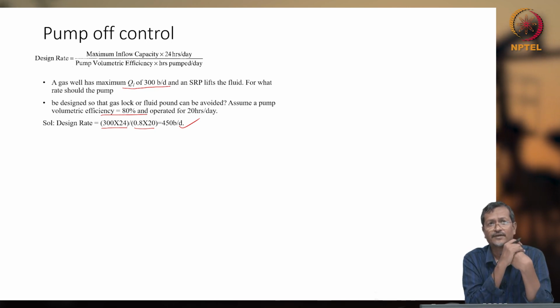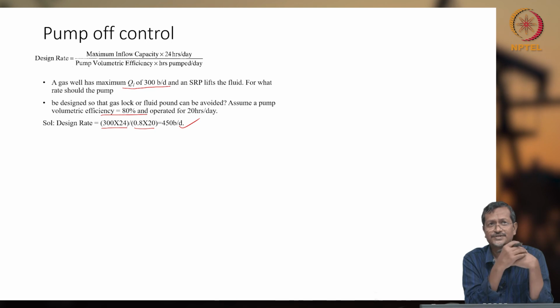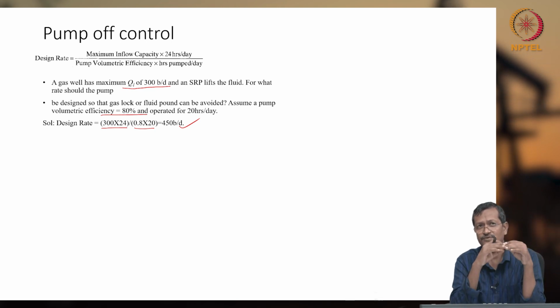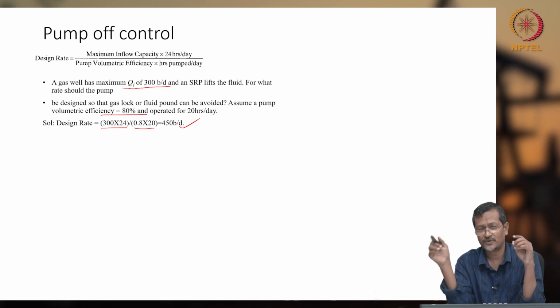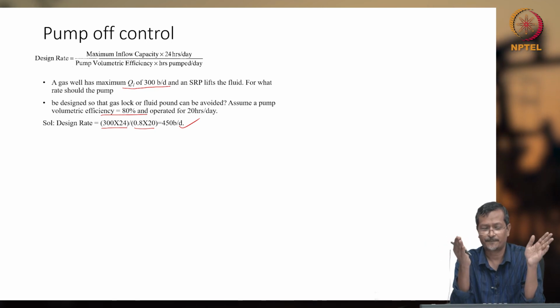These days, variable frequency drives are also there. Using a variable frequency drive, you can change the electrical frequency. Electrical frequency will change your motor frequency. The motor frequency further will reduce your gearbox speed. So gearbox speed means your whole SPM, or strokes per minute, will be reduced. When you are changing strokes per minute, still fine.